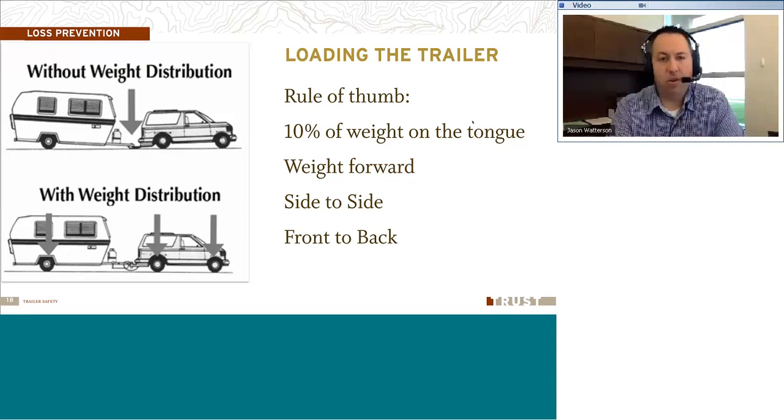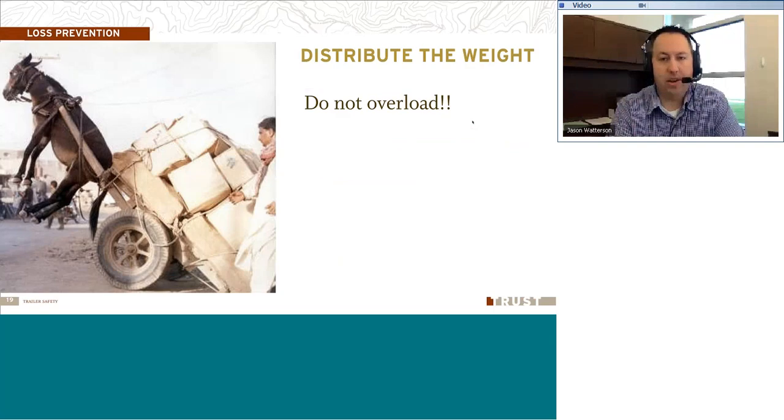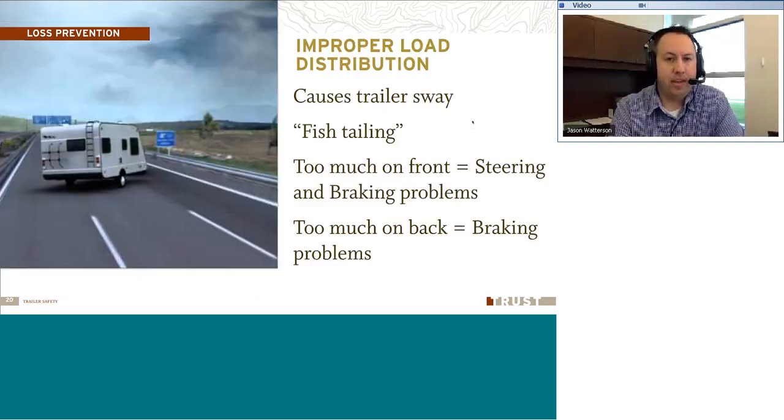Remember, just don't overload it. You don't want to overdo it and have something break. You don't want to have something come loose or break the trailer or cause an accident because you took too much of a load on a trailer that your vehicle or your trailer wasn't able to handle. So don't overdo it. Don't overload there. And then talking about the load distribution, again, that causes some fishtailing.